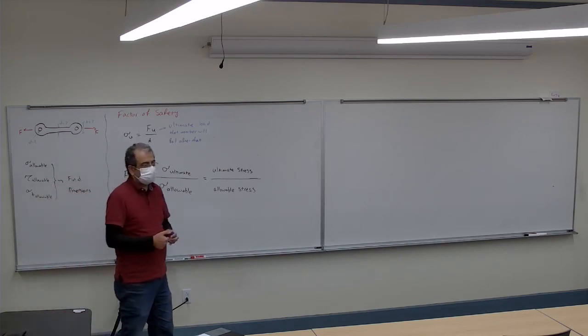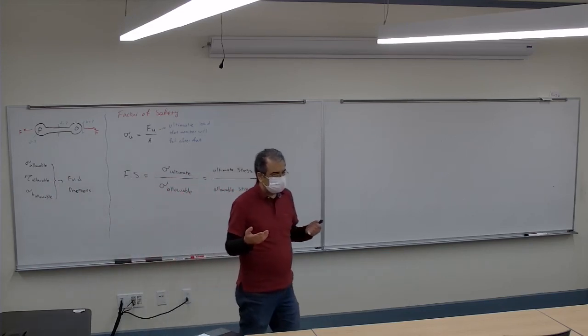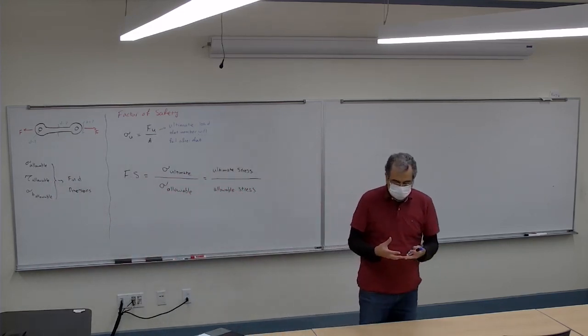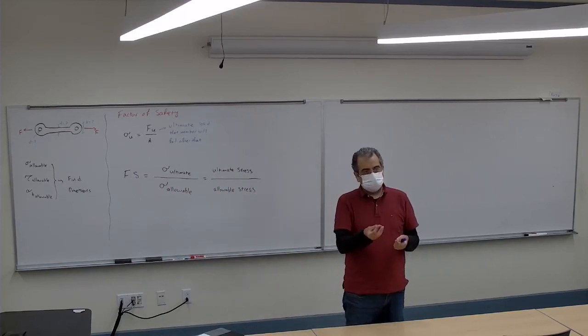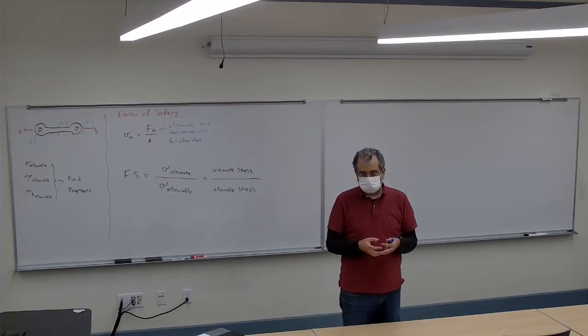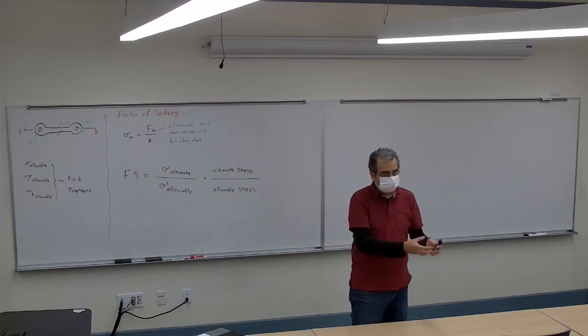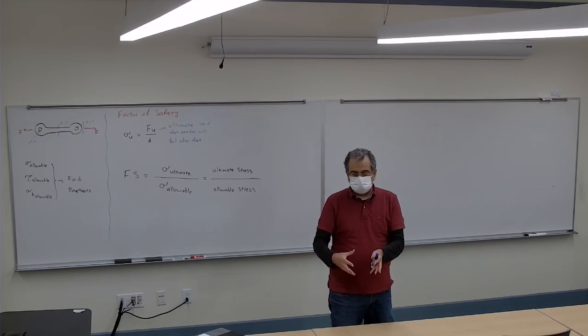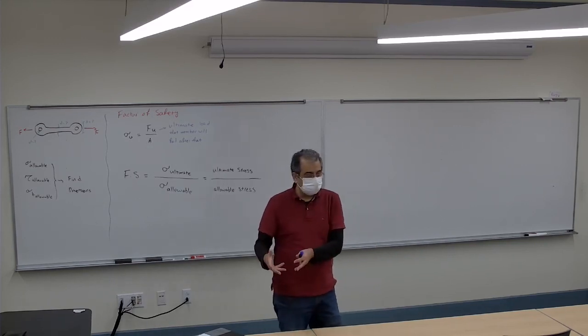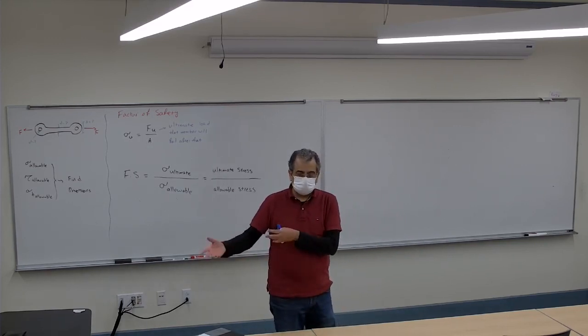How you're going to decide it, again, many factors are involved in defining the factor of safety. For example, if I'm designing a single family home, the factor of safety I'm using in design is different than if I'm designing schools, and it's going to be different if I'm designing a hospital, and different if I'm designing a nuclear plant.